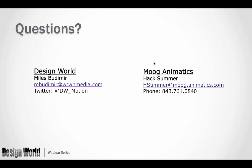Now, I also mentioned the 50 volts low voltage spec, or below shock level voltage for OSHA. There's actually one other specification I did not mention. It's a water specification, such as in displays, whether it be a fountain or a water display of some sort where people can actually touch the water. There's a lower voltage spec at 30 volts. All of our products have 24 volt rated torque curves. You can look it up and see what your torque would be if you kept it below 30.